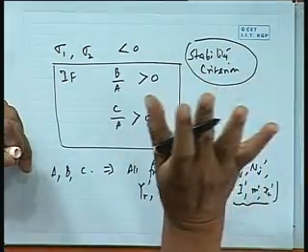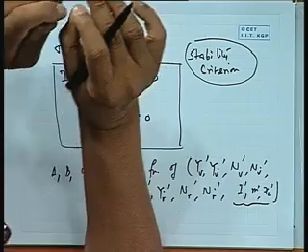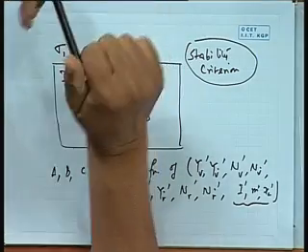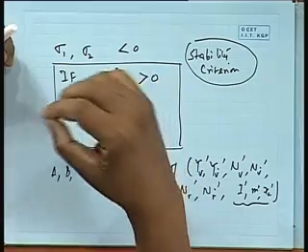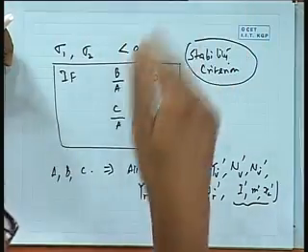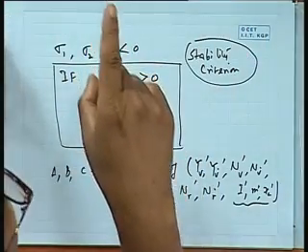For a ship with controls fixed, I do not have a control line, but in such a case for the ship to come back to its original path of straight line. Remember that it is only straight line stability, because when v is 0, r is 0, which means it is not further turning, but it is not changing its heading.